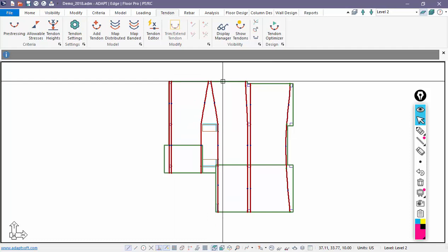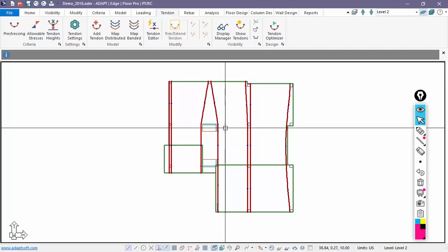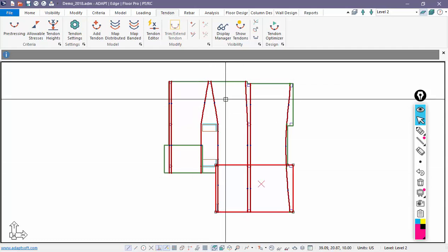And so if we take our slab, and I'm actually going to be a little bit conservative, if we take the maximum thickness of this slab, you could also do this by region, but we'll say we have 8.5 inches times 36 inches, that's 306 square inches, and if we multiply that by the target pre-compression, I'll use 150 again, we get a force of 45.9 kips is required every 3 feet. So we're going to create a tendon, and if we take that force, we're going to divide it by our assumed effective force, which is 26.7.